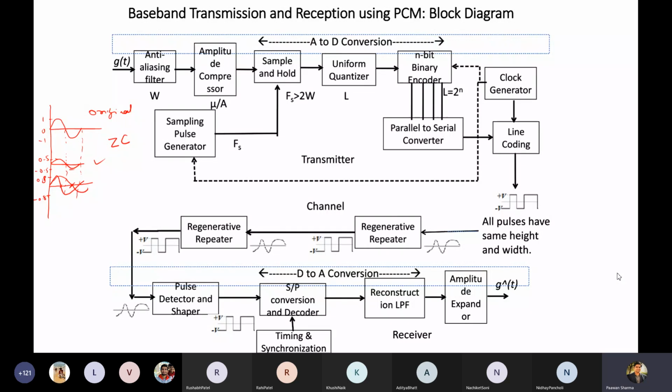So for that, you have to understand what is the reason of distortion. The prime reason for distortion is the channel characteristics, right? If you understand the channel characteristics properly, you can undo the effect of distortion by applying the inverse system transform, inverse system response. If the channel is introducing distortion with a certain model, just inverse of that model if you apply, it will try to undo the effects of distortion.